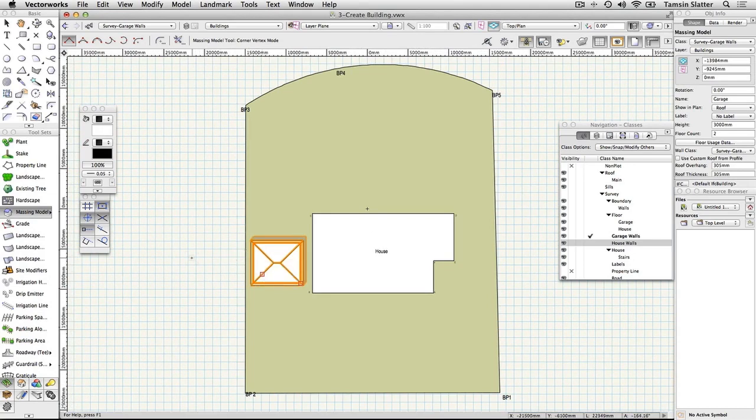The massing model is created. If you have Renderworks, the walls and roof will be textured differently, because we've applied different classes to them. I've previously edited these classes to apply my chosen textures. You'll see how to do this later when the main building is finished.